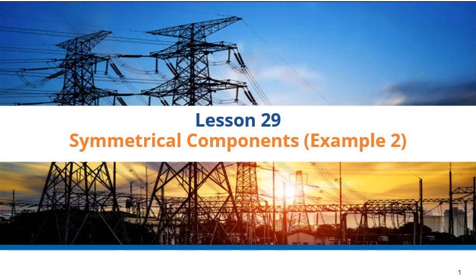Greetings, welcome to lesson 29. In this lesson, I'll go through a numerical example in which, using the symmetrical components method, I'll find the currents through a balanced set of three impedances that are Y-connected and have a floating neutral point.